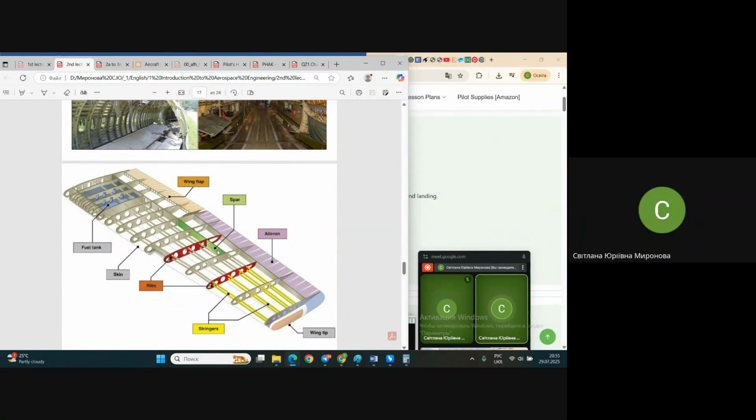In the wing of highly loaded structures, like supersonic fighters, which fly with very high velocities and do maneuvers and so on, they are short winged additionally because it's more efficient for drag. You do remember, I hope, that short wings at higher speeds have less drag than long winged aircraft. And in this case, there may be seven and even a dozen spars inside.